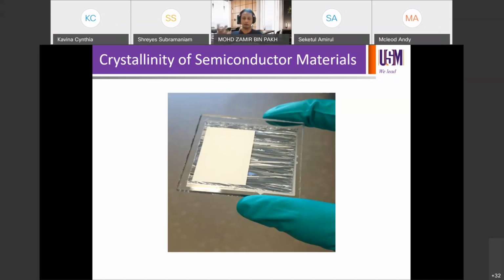If you work on anything with laser for your FYP, for example, perhaps you can relate more. So you just scan, and right after the scan, upon solidification, you turn the amorphous region into polycrystalline region, and then it will follow. So I scan from right to the left, so you can follow that. You can see that the grains are elongated in nature. They are lengthened, extending to the left. You will follow, because that's the mechanism of the scan.